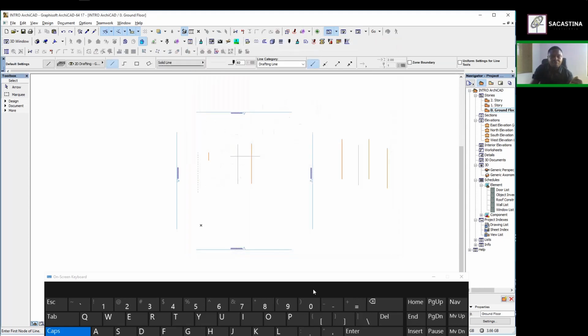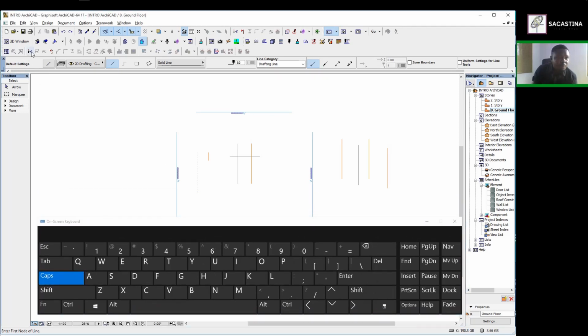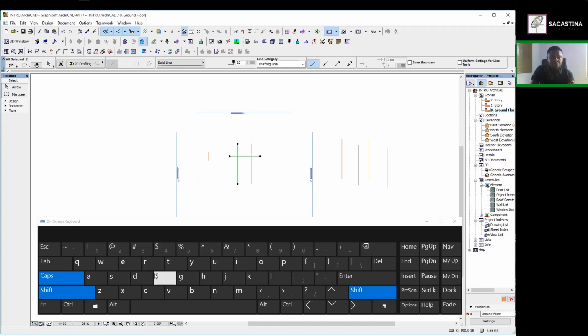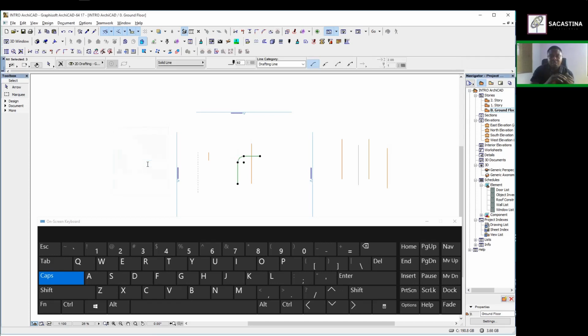Now you can see all of them now have a shortcut key. When you go closer to them, you can see the shortcut keys are there. Very simple. Now when you select this particular place, for example, let's select this one and say Shift 4, it will ask me what distance I want to make them. Let's say 1.5 and I'll say okay. First of all, it will merge them at one point and then chamfer it to what I want.